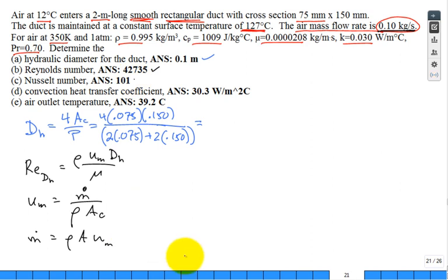How are you going to calculate the Nusselt number? Well, use a correlation, one of those correlations. You want to use Sieder-Tate, Dittus-Boelter, what is it, Gnielinski? I butchered his name, I'm sure. I would use Dittus-Boelter, it's easiest.